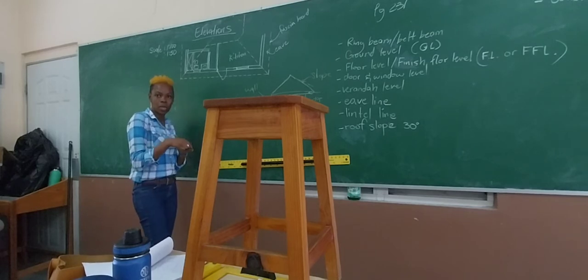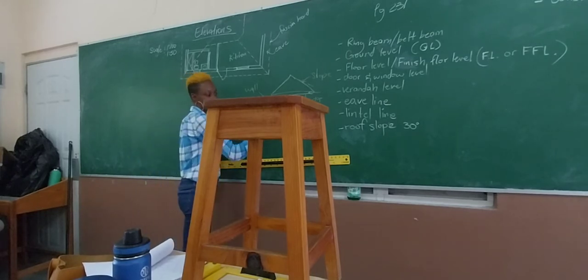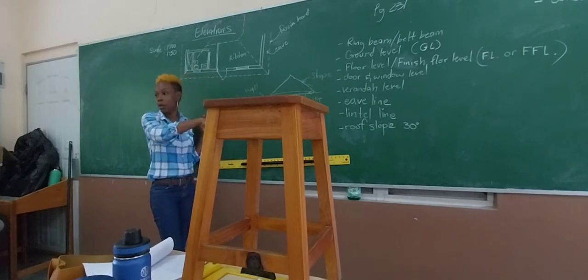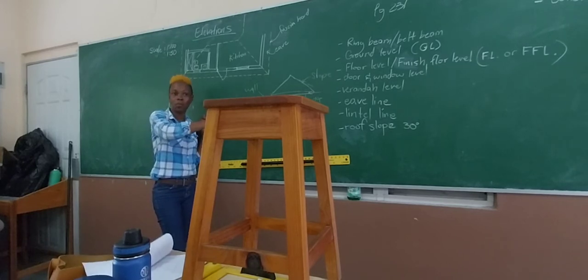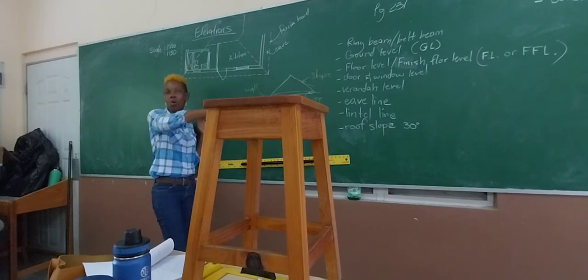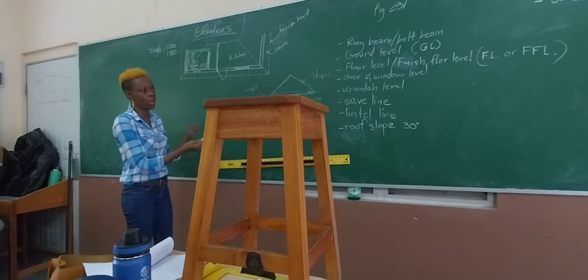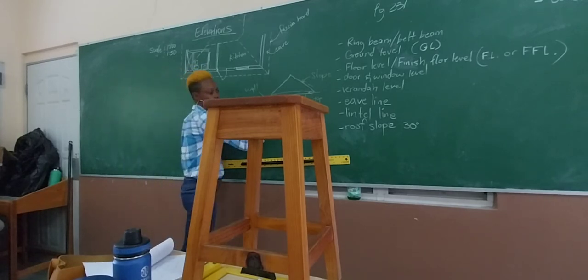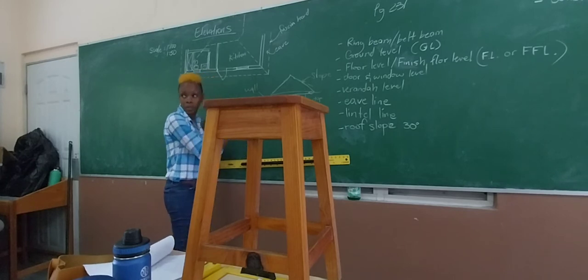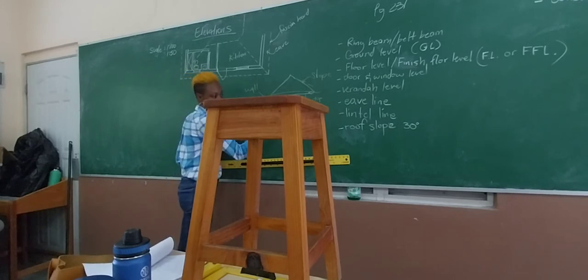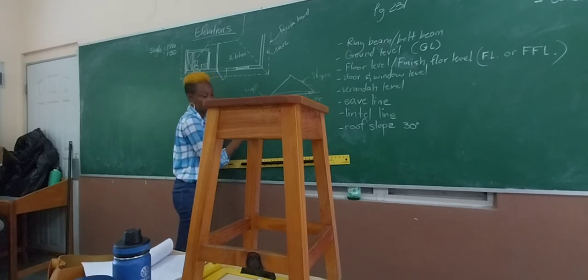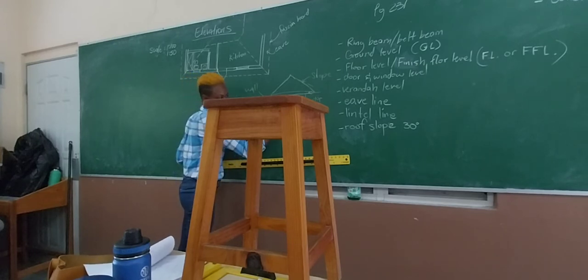Now when we start the drawing, I'm going to explain the concept of this line. This line here should not be a solid line, because if you're outside of a building, unless your building is transparent, if it's glass, then you will see the floor. If you're outside, you cannot see the floor. Only if there's a door, you know, okay, that is where your floor level will be. Alright, but another elevation where there is no window, you cannot show a floor level there. Alright? However, on all of the drawings, then you must have a floor level. So this here will be a dashed line, but we talk about that when we actually start the AutoCAD one.